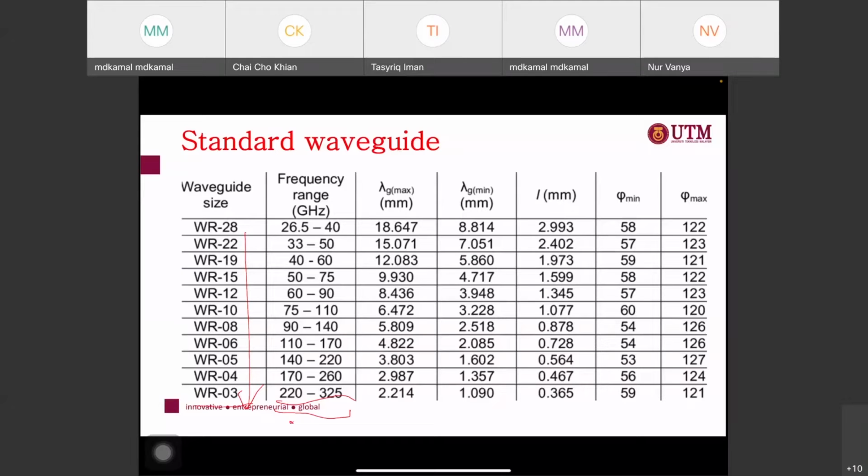That's why if you want to use terahertz applications, you will find that the guided wavelength or the aperture size of the waveguide is very small. We don't have it here in India because that particular waveguide is very, very expensive, and it is made from gold, or coated with gold.